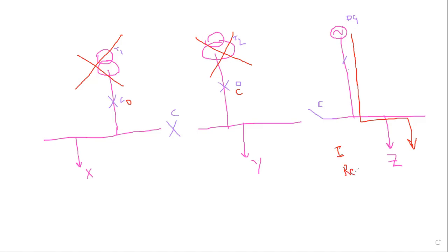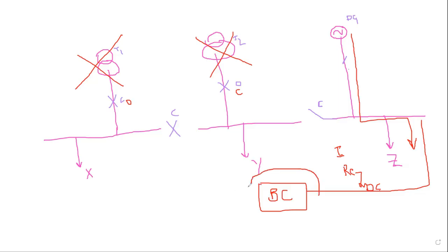So for all the relays, I actually require the DC supply. How will I get the DC supply? From this DG set generator, I have one AC supply which is connected to the battery charger. One of the loads in the DG set is connected to the battery charger. This battery charger converts the AC to DC, with a rectifier inside it, and this DC is distributed to all the relays.